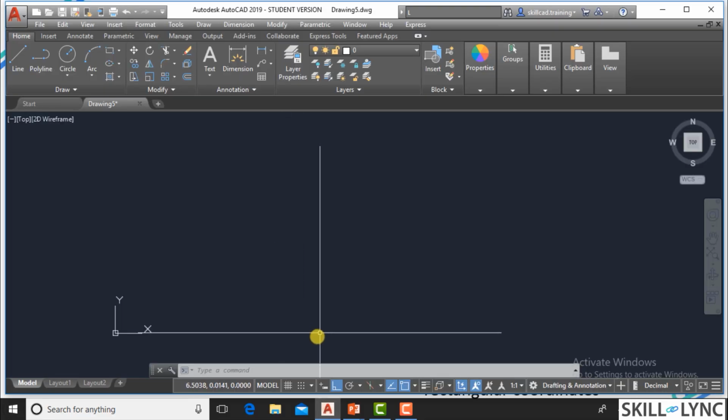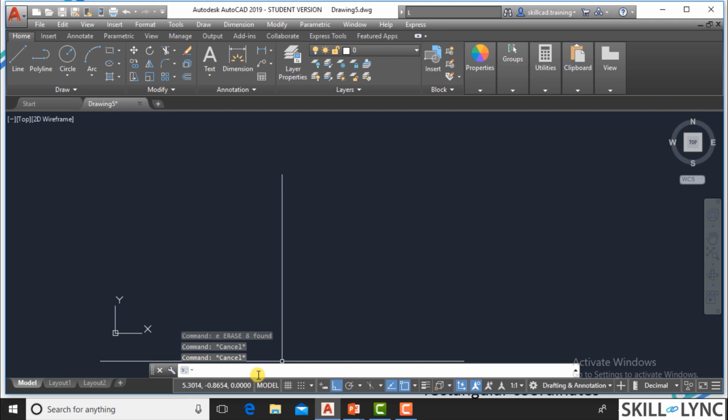Here one special character will come in. With the line tool, for the first point, let's say I go with 1 comma 1. Now there's a character called @. You type the @ with shift and the 2 button. What @ does is it shifts the coordinate origin from 0 comma 0 to the last point.